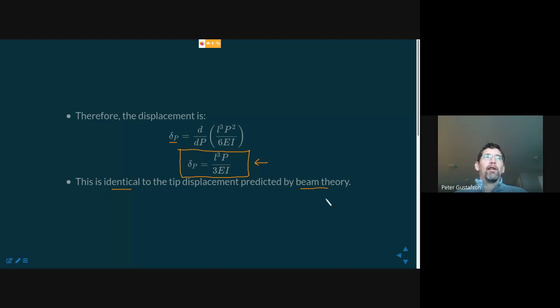And oh, by the way, you note that I wasn't calling for any boundary conditions in this description. The boundary conditions sort of took care of themselves along the way. Hence, because of those two things, we don't have to worry quite as much about the boundary conditions, and we're differentiating rather than integrating. This is easier. And you may not need the displacement everywhere along the beam.